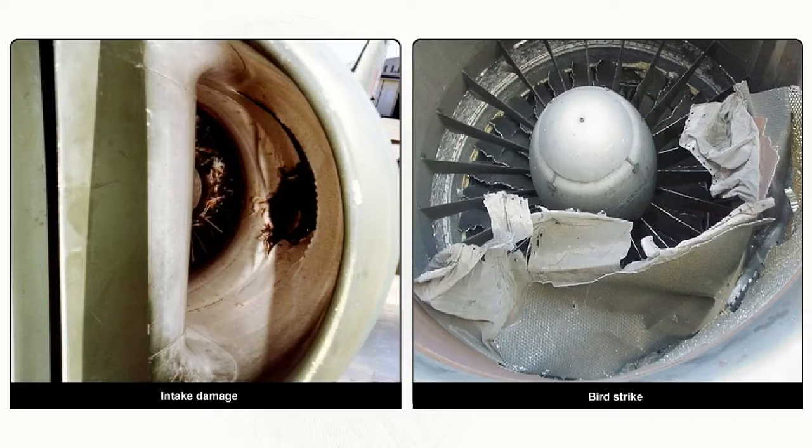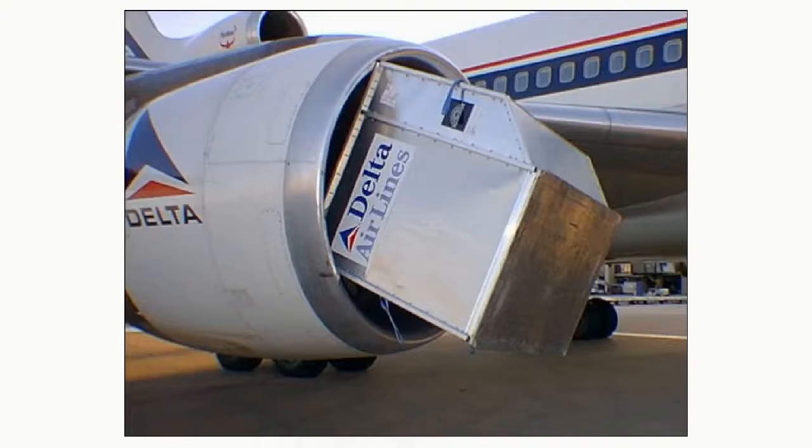Damage to the intake, or any roughness inside the intake, may cause the incoming air to be turbulent, which may disrupt the airflow into the compressor, causing it to stall or surge. It's particularly important to inspect the engine intakes before flight for any form of damage, uneven skin panels, surface roughness, etc. Damage to compressor blades is invariably caused by ingestion of foreign objects.